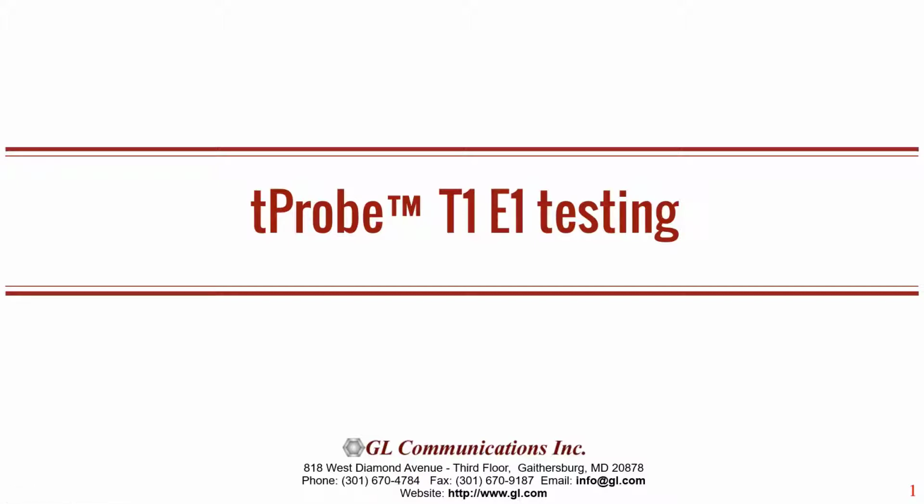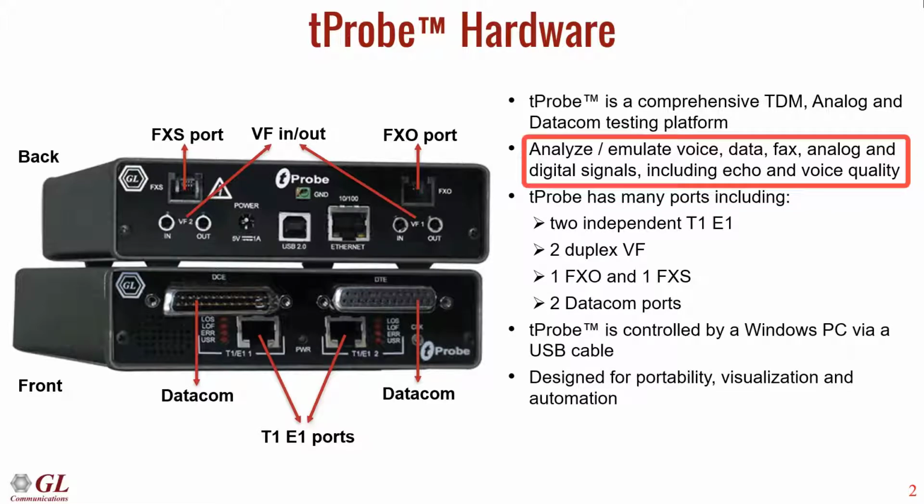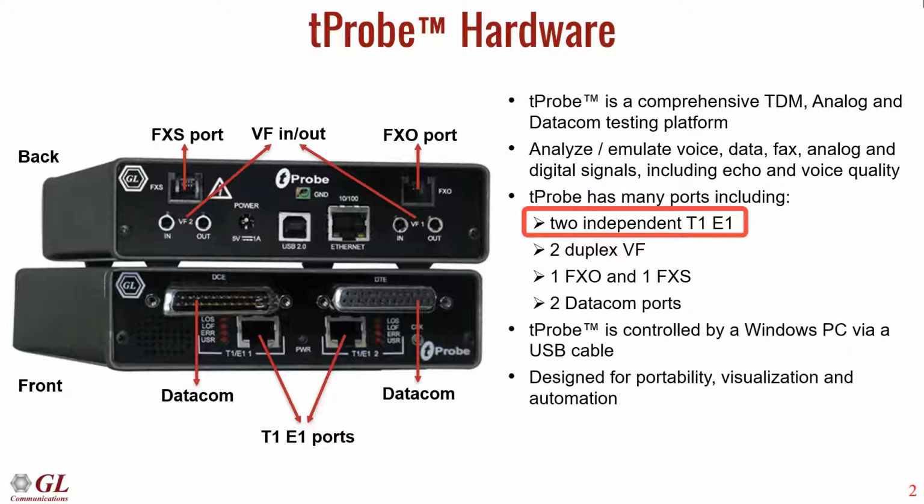In this video, we will demonstrate the tProbe, which is our versatile hardware platform for analog, TDM, and Datacom telecommunications testing. The tProbe can analyze and emulate voice, data, fax, analog, and digital signals, including echo and voice quality. The tProbe has many interfaces, including two T1E1 ports, two voice frequency or VF ports, an FXO and an FXS port, and two Datacom ports.